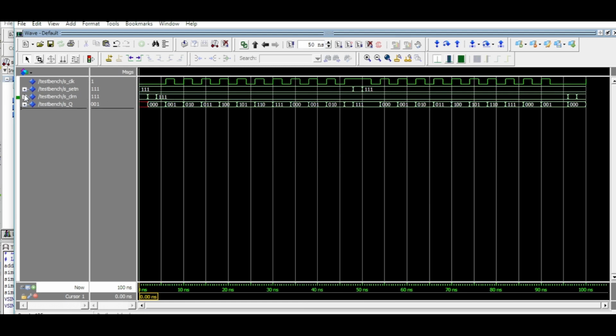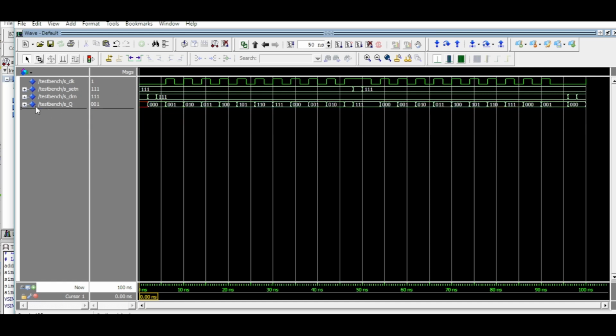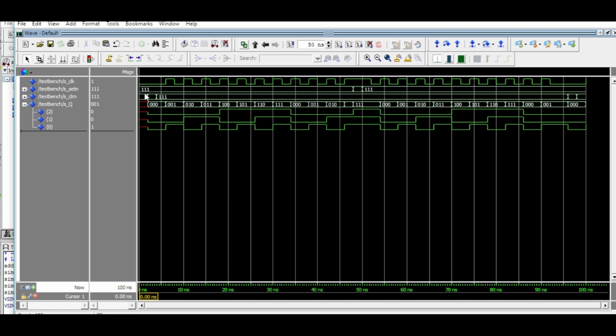So we could run through this with our code. What we did was initially we made our clear signal active. So we cleared each one of the flip-flops at this point. Now, nothing changed in our output at that point. Things were uninitialized before then, but when we cleared, our output was forced to 0.